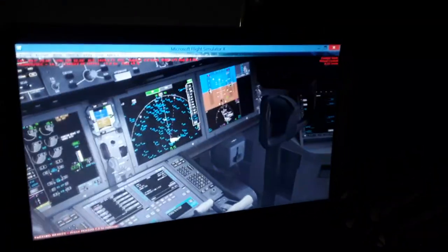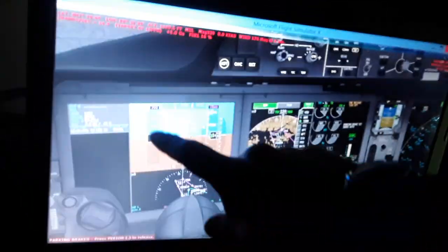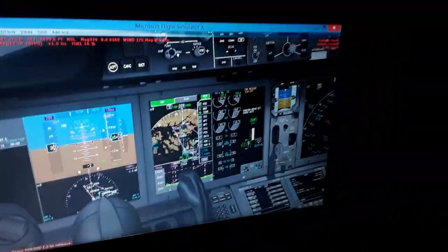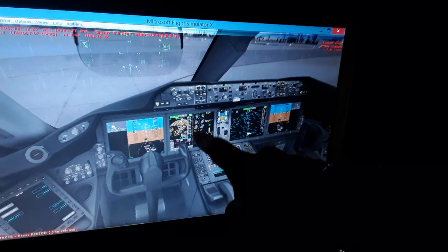So you can see over here we have the primary flight display, as I told you, the indications, the navigation display. So I talked to you about the primary flight display. Also the autopilot flight director system panel, which changes the values, and you will see them displayed in the primary flight display. We have also the navigation display. The navigation display displays the GPS position, the inertial reference position of the aircraft. We have the magnetic heading and track, the magnetic north pole and true north pole, and then magnetic variation depending on where we are in the world.